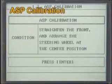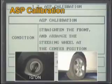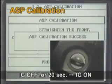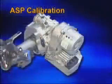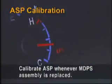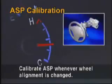At the initial item of the scanner, set the steering wheel to the straight ahead, that is, within plus or minus 5 degree range, and press Enter in IG on state. After being IG off and waiting for 20 seconds, set IG on, then the steering angle initialization is conducted. If the steering angle initialization is not conducted after replacing with a new MDPS assembly, then the EPS warning lamp blinks. However, when a used MDPS assembly is replaced, the lamp does not blink.